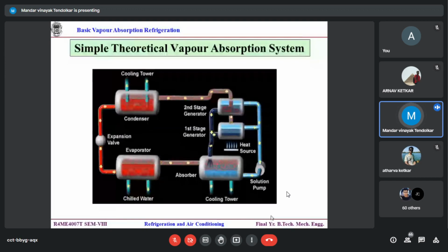Now you can realize that the compressor work is related to the vapor, the gaseous part, where the volumetric changes are very large. So PDV work is large. For the pump, it is the liquid part. PDV is very small. We consider liquid as incompressible, so pump work is negligible because you are dealing with the liquid part.